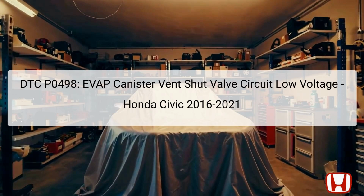The Diagnostic Trouble Code, DTC P0498, indicates a low voltage condition in the EVAP canister vent shut valve circuit. This code is pertinent to the 2016 to 2021 Honda Civic, and it specifically relates to the component responsible for managing the flow of fuel vapors from the fuel tank to the charcoal canister.